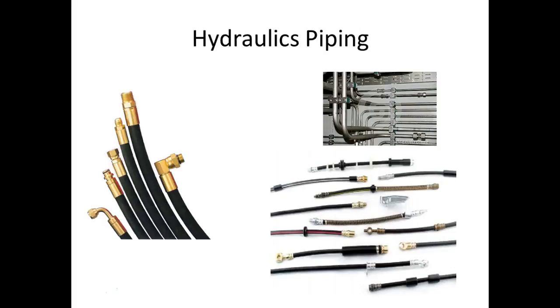So your high pressure tubing is very expensive. I don't know if anybody's ever had to change the high pressure tube out on the air conditioner on your car. Be ready. Those things are very expensive because they're reinforced. They've got all types of layers. They'll be real round, but the inside is really little. They'll keep the pressure in, not the cold in, the pressure in.